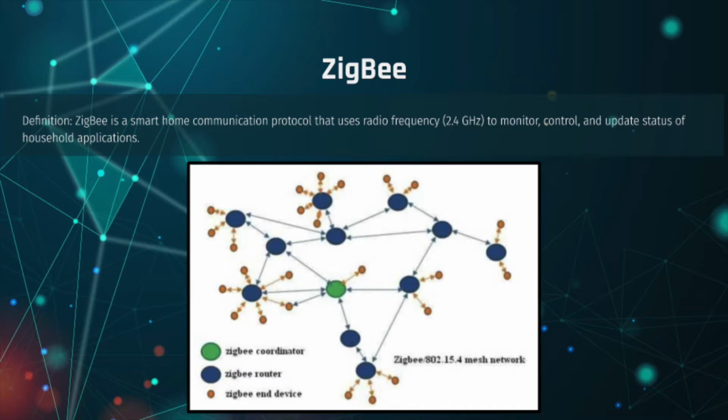When forming the Zigbee network, the coordinator searches for a suitable radio frequency channel, which is usable and not interfering with wireless LAN frequencies in use. This is because wireless LAN also operates in the same 2.4 GHz bands. Next, the coordinator starts the network by assigning a PAN ID to the network. Assignment is done in 2 ways. One is manual, which is pre-configured, and the other is dynamic, which is obtained by checking other PAN IDs of networks already in operation nearby so that the PAN ID does not conflict with other networks.